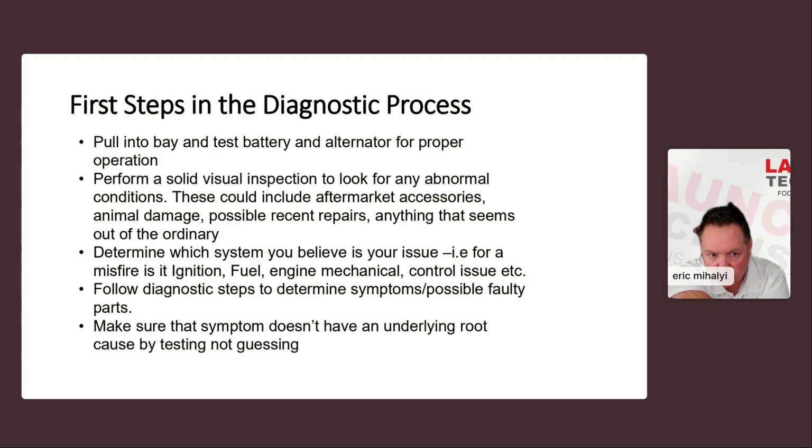So really, really important that you test the source of the electrical power, okay? Because you can have quite a bit of problems with modern cars because of that issue, that now we are reporting battery life back to the car, right? There's a thing that we refer to as load shed. And what happens is the car starts making determinations on what's important that it needs the power for.